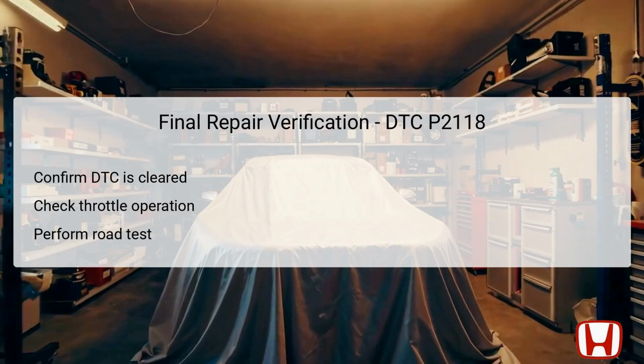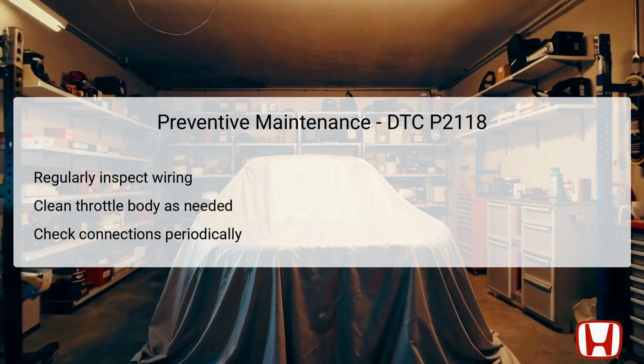While resolving DTC P2118 is essential, implementing preventive maintenance practices can significantly reduce the likelihood of encountering similar issues in the future. Regular inspection of wiring associated with the throttle actuator is vital. This will help catch any fraying or corroding connections early. Cleaning the throttle body as part of routine maintenance can prevent buildup and mechanical failures from occurring. Lastly, make it a habit to check connections periodically to ensure that terminals are tight, clean, and free of debris. Such measures not only enhance vehicle reliability, but also contribute to overall engine performance and longevity.